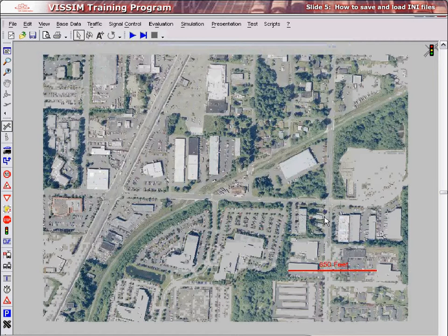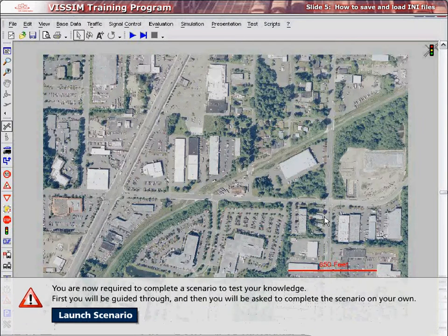If you want the settings to be automatically opened when you open the INP file, you will need to save the settings to the vSim INI file within the INP directory and open the INP by double-clicking on the file. If any other name is used, you will have to manually load the settings. If you want the settings to be automatically loaded whenever vSim is started, you need to save the settings to the vsim.ini file within the vSim exe directory.